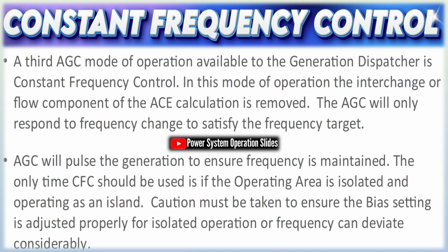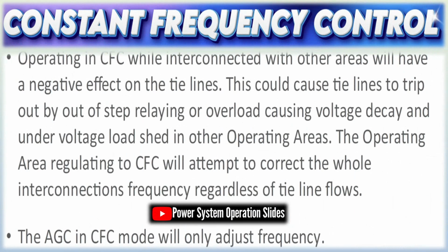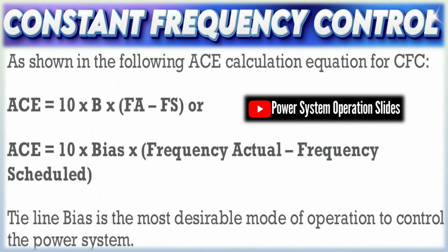Power plant generation dispatcher interaction. AGC bridges the gap between the power plant's operational units and the central dispatch. In practice, dispatchers use economic and operational criteria to set generation schedules and tie line power targets. AGC translates these targets into real-time control actions.